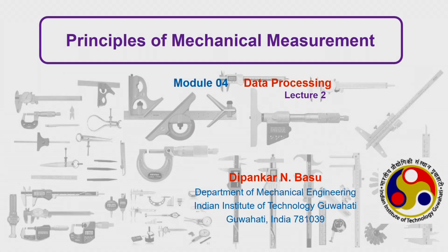To measure the change in resistance, we subsequently convert it to another electrical output, generally a change in output voltage, using bridge circuits. Therefore, measurement of impedance, which can be resistance, inductance or capacitance, is a very common mode of measurement for different parameters. We discussed in the previous class the measurement of pure resistance based DC circuits in the form of the Wheatstone bridge, and also several AC circuits which allow us to measure resistance, inductance or capacitance, like the Wien bridge or Maxwell's bridge.